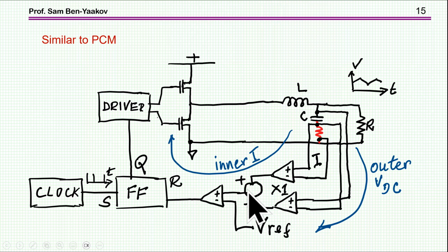Now, what we see now is that the original ripple is this one, and now I'm adding this slope compensation. Well, I may have exaggerated with the amount of slope that I've added, and this is just to emphasize the fact that when the ripple is higher, and since I'm looking at the peak value, then the average of the output is away from the 5 volt.